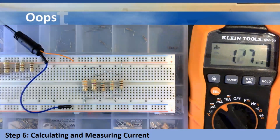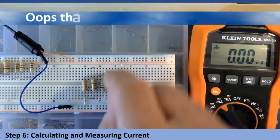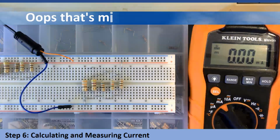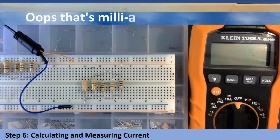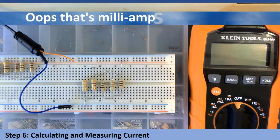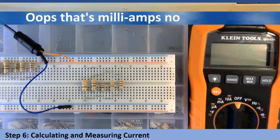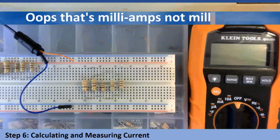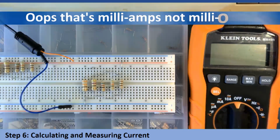You're going to do the same thing, where you're going to interrupt each of these resistors and then restore it and measure the current flowing through each resistor. For the next part of the lab, you're going to conduct an experiment to find out what happens when you stress a resistor beyond its designed wattage rating.